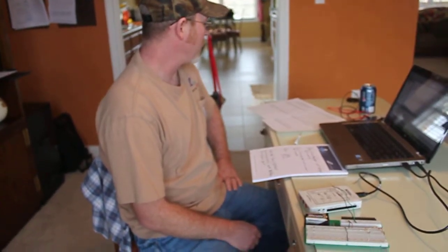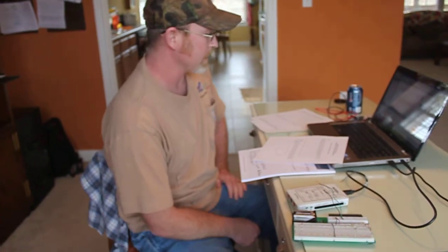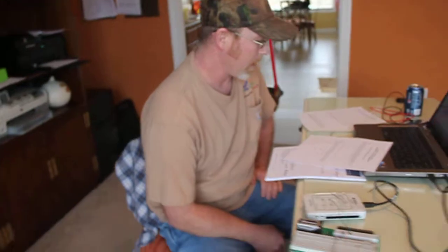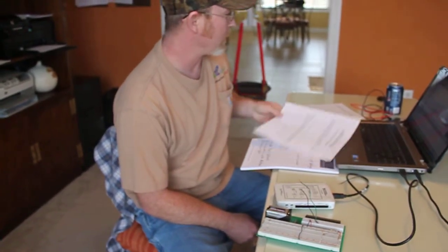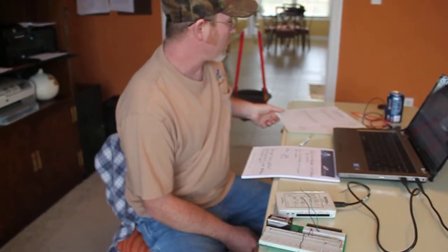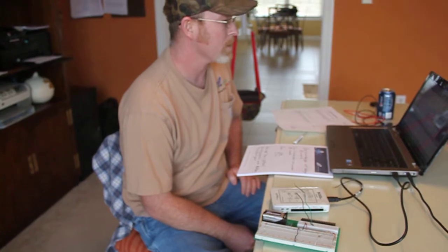EE304, and this is lab project number 1 using LabVIEW and MyDAC. And what we're trying to do is we want to design a circuit that has a 3.9K ohm Thevenin equivalent, and we want to take a few measurements of that circuit, and ultimately in the end we want to prove the max power theorem happens when the Thevenin resistance equals the load